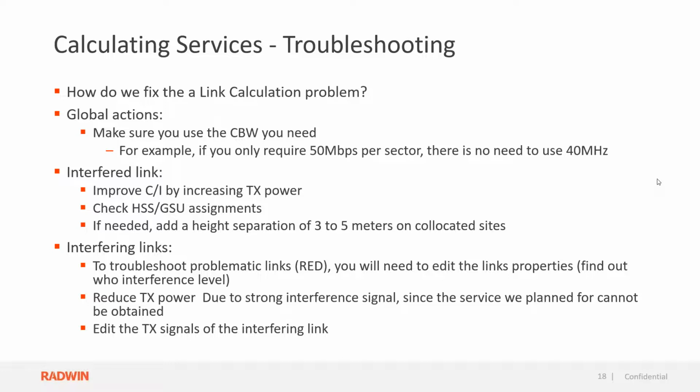Now, many times you ask me how to simulate interference. And when you are reducing the TX power, it's not a real simulation of interference. When you are trying to simulate interference, the best way is to add another device or another radio nearby on the same tower or the same area, which is transmitting towards or nearby the same radio that you are using.